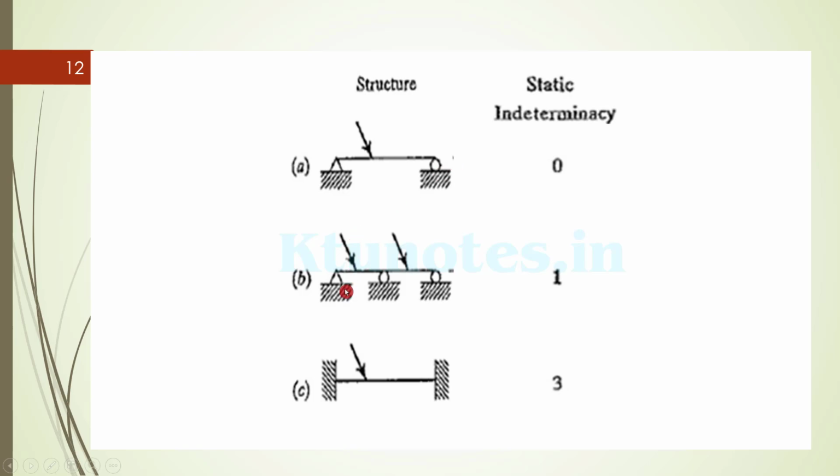In the case of an additional support, here actually 3 supports are there. Here, the force being inclined, there will be 2 reactions at the hinge, a vertical reaction as well as a horizontal reaction. So 2, then here 1, only vertical, here 1. So 2 plus 1 plus 1 will be 4 unknowns, minus 3 equations will give you 1 degree of indeterminacy.